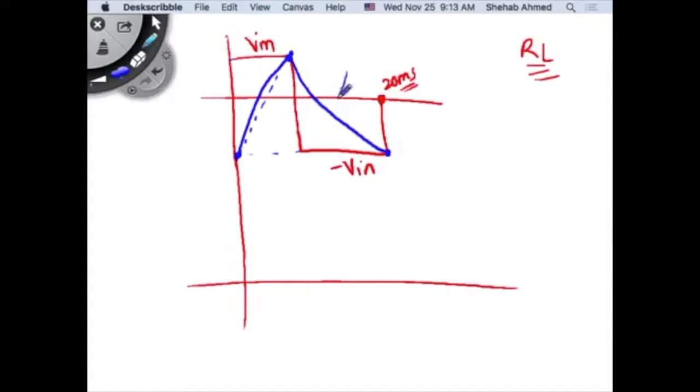Is that the same as the Fourier series for this waveform? No. They will have some harmonics that are in phase. So they will have maybe the fundamental. They may have a third. They may have a fifth. But definitely, this square wave has significant transitions here. That means that there's a lot more harmonic content in these fast transitions than this slow transition. I don't have the Fourier series for this blue waveform. But since the waveforms are not identical, there's a difference between the harmonic content. That's the basics, just by looking at the waveform.